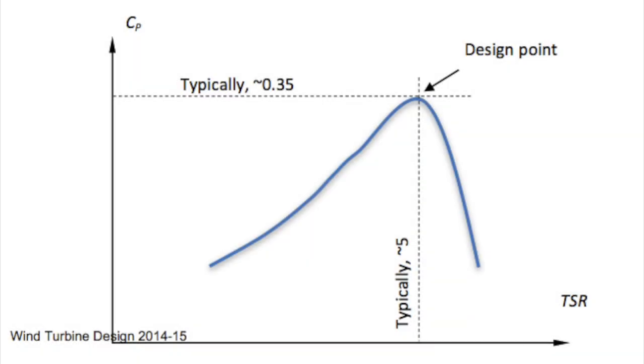Since our turbine does not use pitch control, as with modern turbines, we aimed at designing for optimal performance between 10 and 12 meters per second winds. Following on from the theoretical background, let us consider the design process. The first step was to choose a tip speed ratio. Based on the knowledge that tip speed ratios for small wind turbines typically vary between 3 and 6, this was